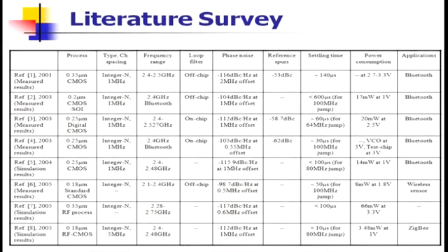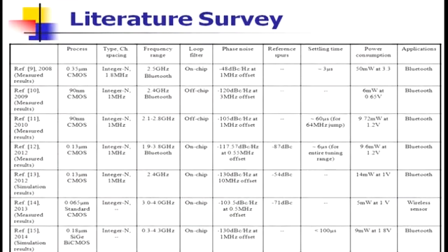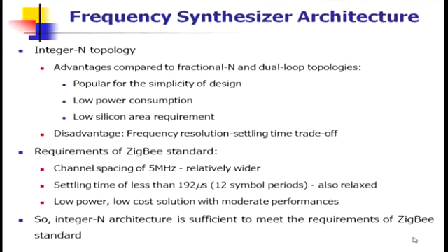Always, if you burn more current, you will get better phase noise, because actually you are adding more power to your signals. That's where your phase noise is getting improved. These are pseudo developments. And if you look at 2014 and so on, remember that it has a simulation result, not a test result, of minus 130, but look at its power consumption: 9 milliwatt of power gives me 130 dBc/Hz, that too a simulation result in 2014. This is for Bluetooth, at 2.4 gig.